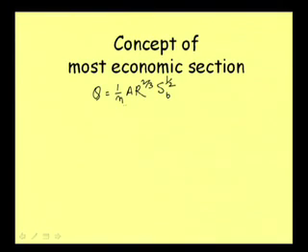So, this is the formula, and here 1 by n A R to the power 2 by 3 is basically the conveyance K. When our conveyance is more, that means it can carry more discharge. Conveyance more means, literally, that it can convey more water. So, our target is to maximize the conveyance.